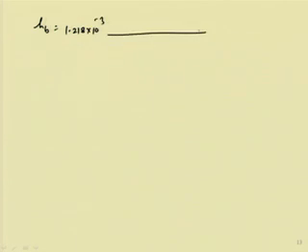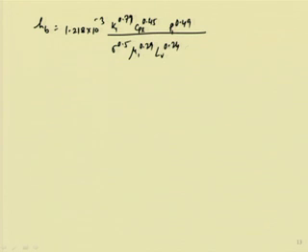This into k_L, thermal conductivity, to the power 0.79, then Cp_L to the power 0.45 into rho_L to the power 0.49, by sigma to the power 0.5, mu_L to the power 0.29, h_LV to the power 0.24 and rho_V to the power 0.24.